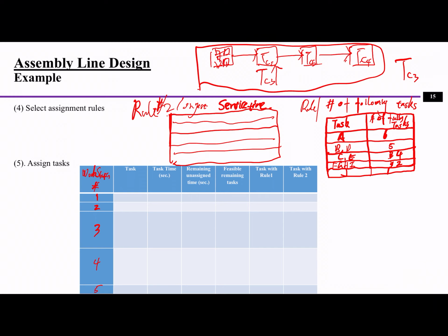each of the workstations, because each task can be really short or really long. If this is, say, 50 seconds, we don't just want to put one task in with only 9 seconds here, right? So we put more tasks in order to save space and also improve efficiency, making it more balanced. This is why we assign tasks to different workstations. Now we know we have stations 1, 2, 3, 4, so our job is to put tasks into these workstations.